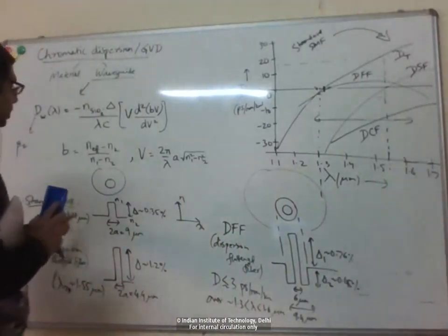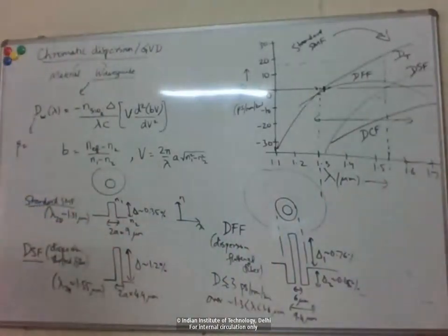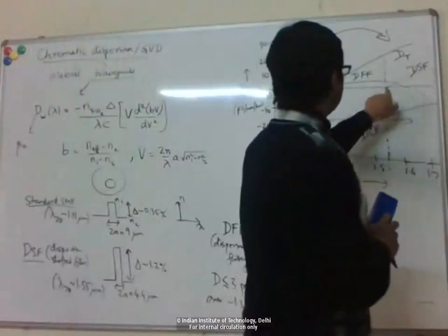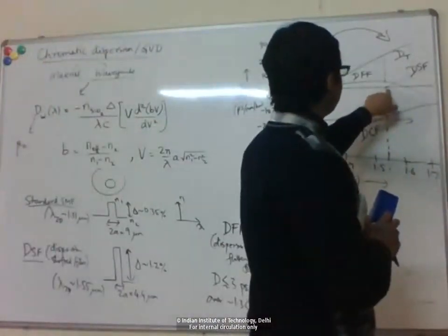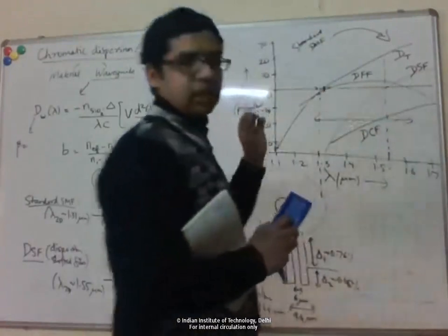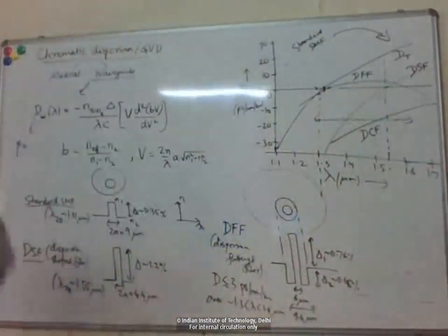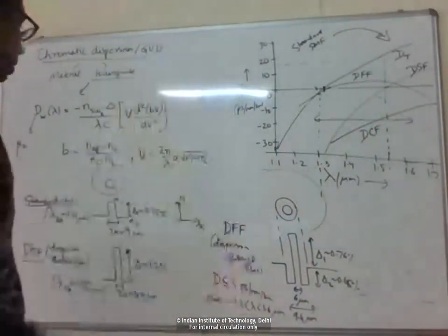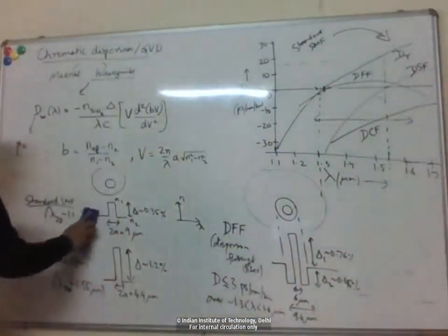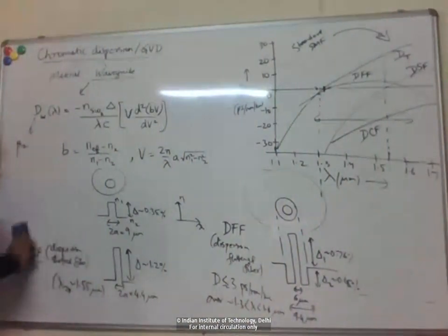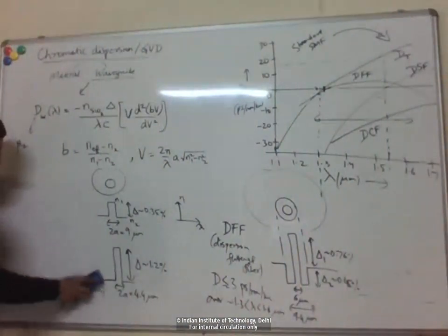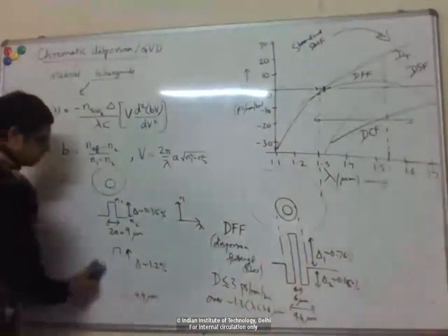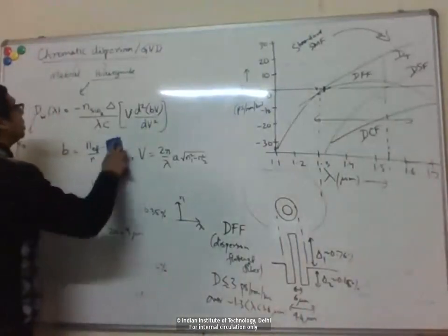Okay, so let's briefly go back to this question: what if D is 0, right? Let's say I'm operating at the wavelength where this D is almost exactly 0. So then can I just boost up my data rate as high as possible? There is no limit? So the answer is no, of course, because now the higher order dispersion starts coming in.